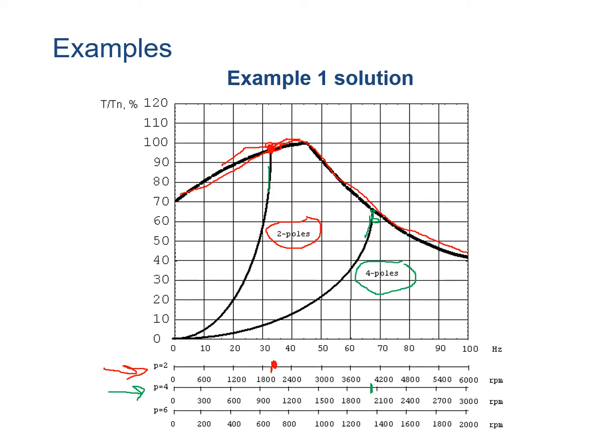But now we see, for example, that in the first case, case number 1 here, our pump's torque is quite close to the rated torque of this motor. So it's maybe a 5% difference. While in the second case, case number 2, we have quite a gap between the loadability of the system and our pump here.